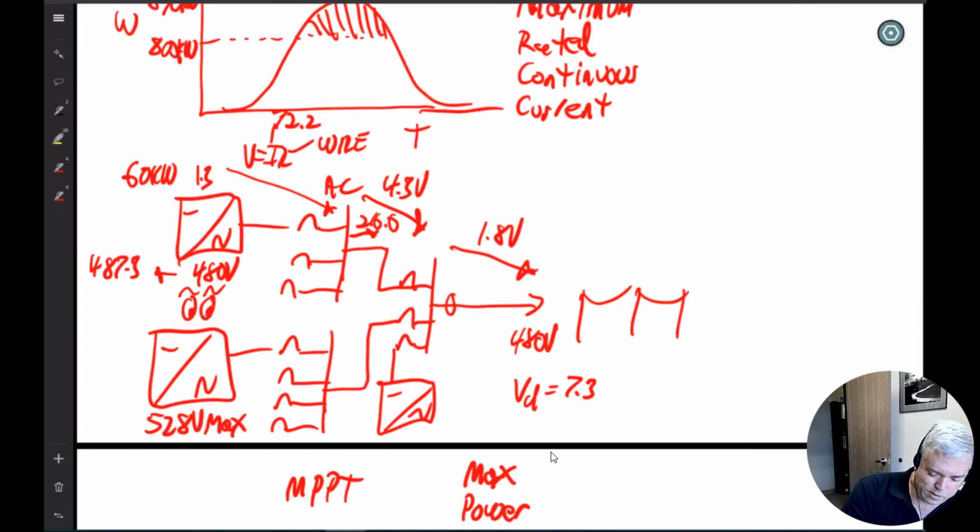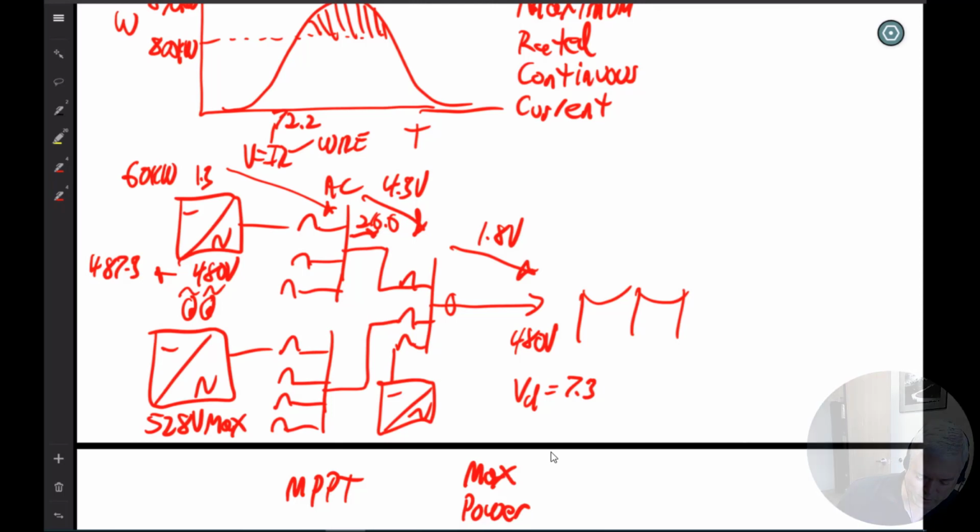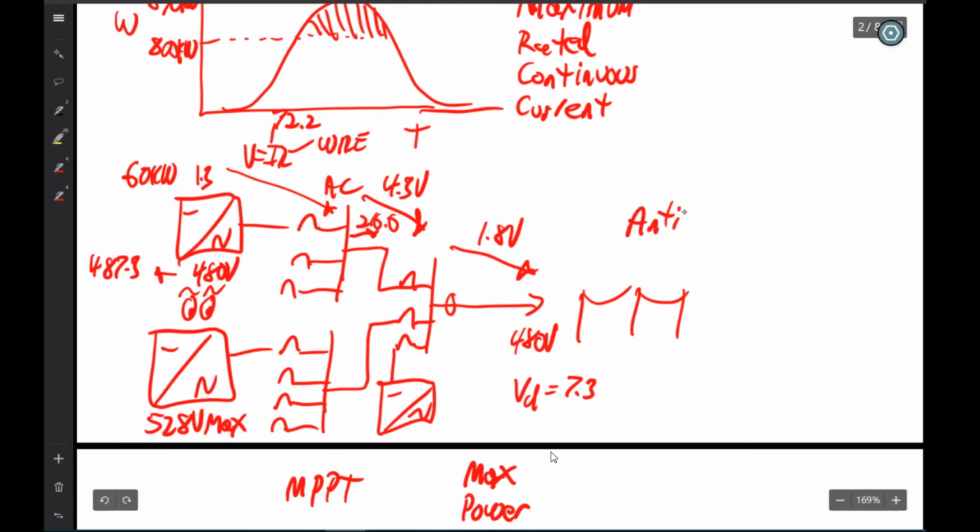So I've got the inverters that are watching the grid and are producing voltage to be able to fall onto the grid at 480 volt. So with voltage drop, they rise up. I want to point out here that it's another form of safety factor, that when the grid goes down, there's a power outage, the inverters don't produce anything. And this is called anti-islanding.